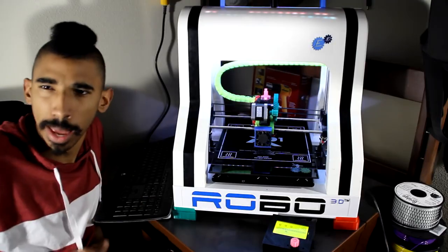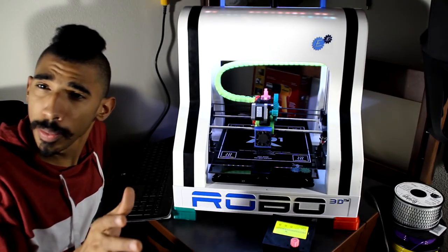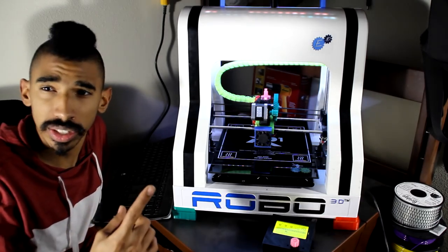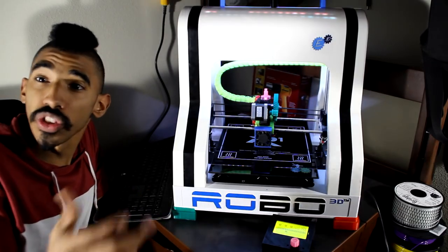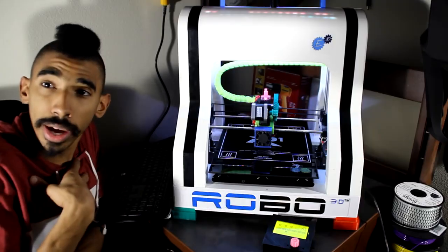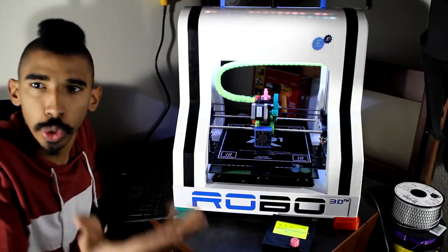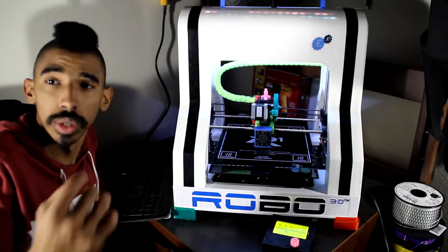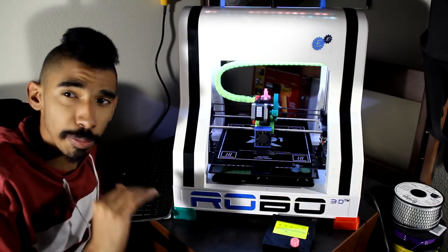You can do this by running an M303, and you can run the command by itself. The default, I believe, is 200 degrees Celsius with 1 cycle. But if you want to change the amount of cycles or the temperature you print at, you can manage those. I recommend turning your fans on before doing the PID tune because a majority of the time you're going to be printing with your fans on, so you're trying to make the scenario as similar to printing as possible.